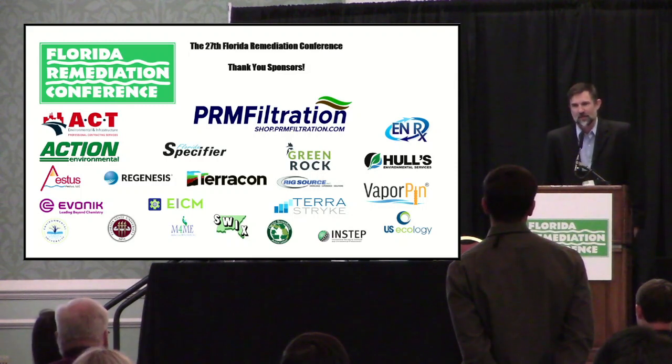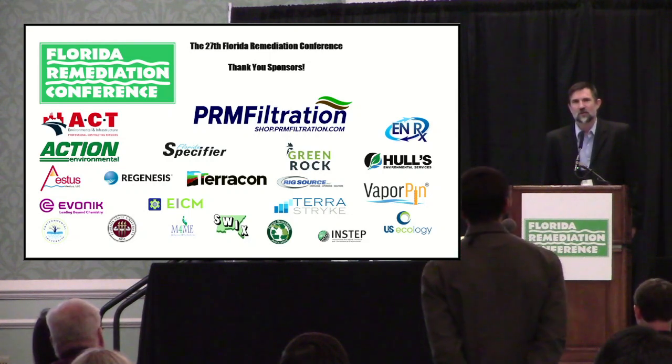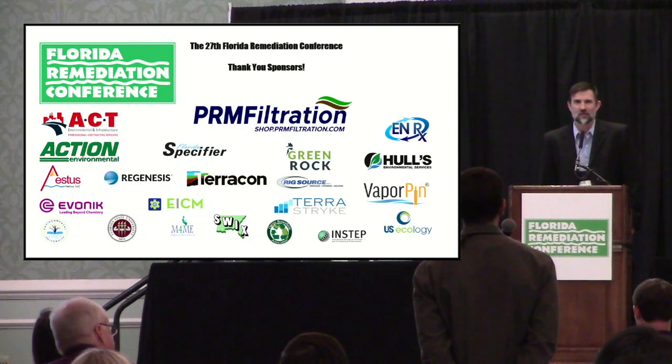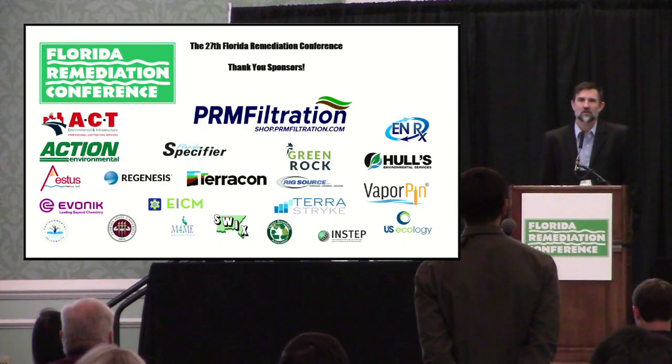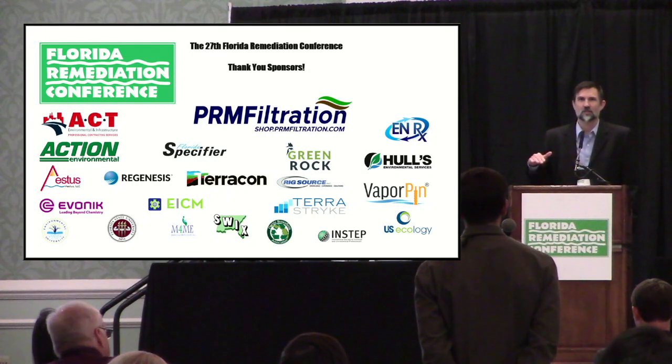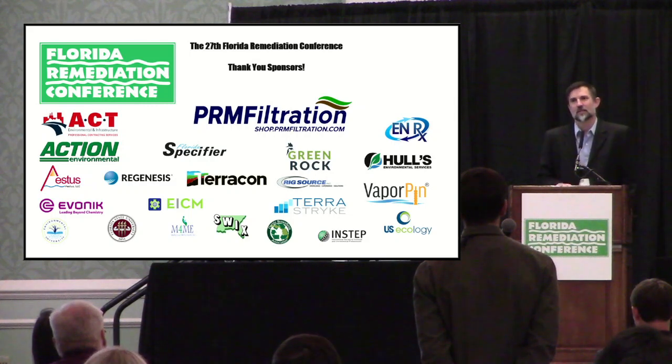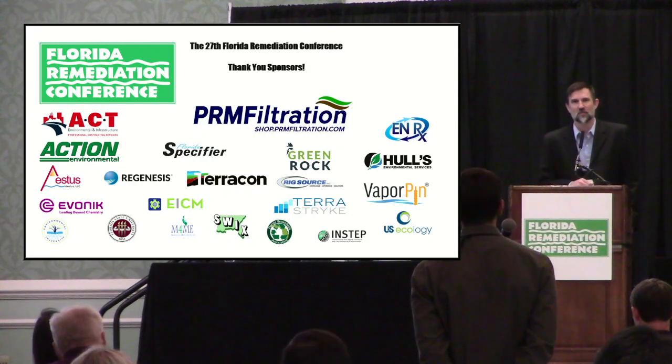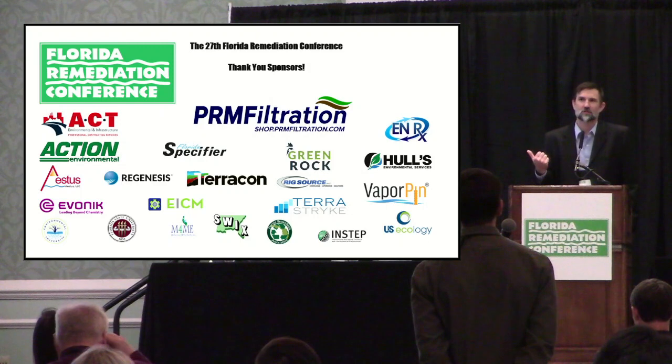Yeah, so that comparison was on bare earth surfaces, so a road or bare soil. If you're going to compare that photogrammetry structure from motion technology to, say, very dense shrub vegetation, or tall grass, or a canopy of forest, and you wanted to compare ground points, you're really not going to be able to get very good ground points with that photogrammetry, the digital camera-based system. But when you're talking about head-to-head on a hard surface, a road or soil, that's that number that I gave.